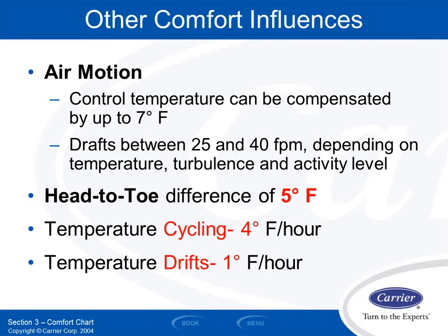So 5 degrees sounds like it's really easy to hit. Oh, I set my thermostat for whatever, 70 degrees and 72 degrees in the wintertime, and everybody's happy, right? Well, it's 72 degrees at the thermostat, but what's the temperature at the floor? So the biggest thing that happens in these cases is mostly in commercial buildings, we have overhead heating systems. That's very common, meaning we have the supply grills and registers at the ceiling level.